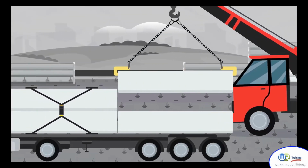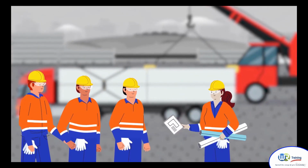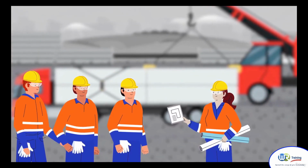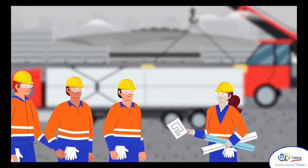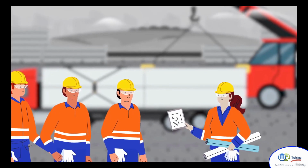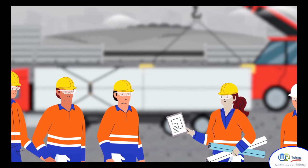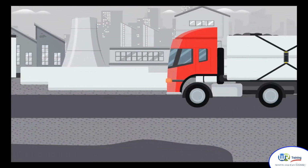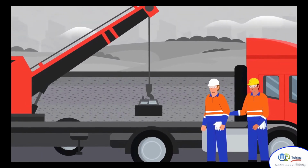In January 2018, a truck driver was seriously injured when he was struck by a suspended load during the unloading of equipment at a worksite. The other workers involved in the unloading operation, including the site's supervisor, dogman, and crane operator, all received a pre-start briefing about loading and unloading at various locations across the site, held relevant high-risk work licenses, and wore full PPE. The truck driver, who arrived later, was not involved in the briefing, and was not fully inducted onto the site by the principal contractor. He had completed one delivery to the site on the day of the incident, and was escorted to a second location where an item of piling plant was unloaded from the truck.